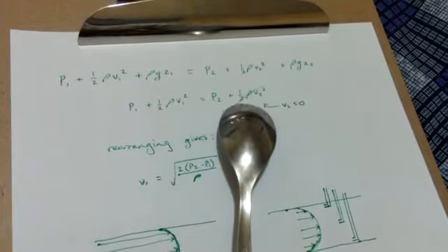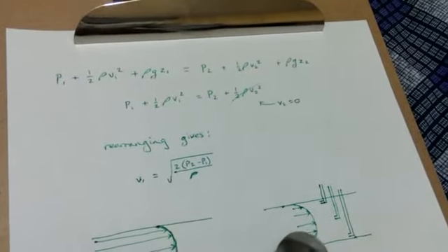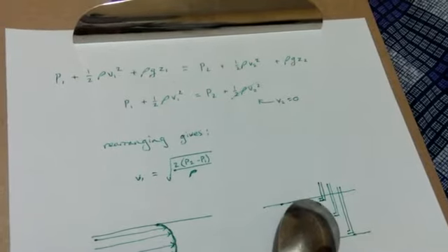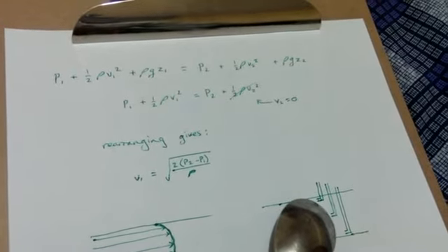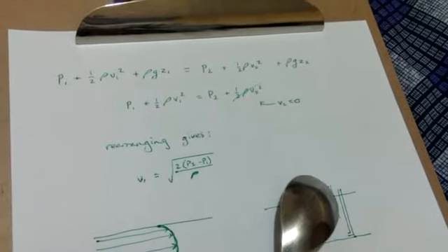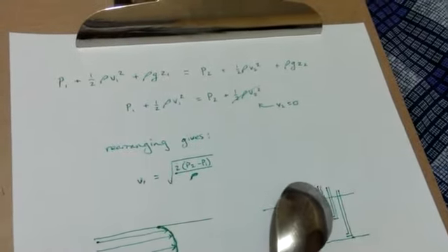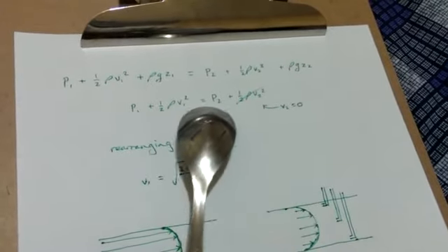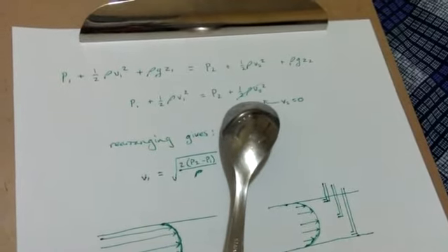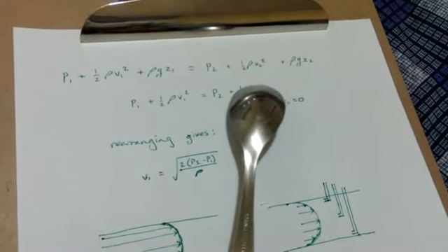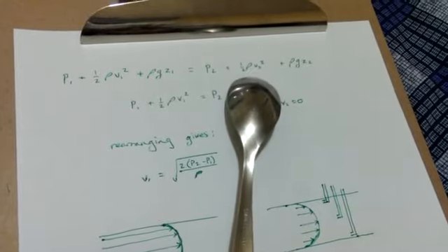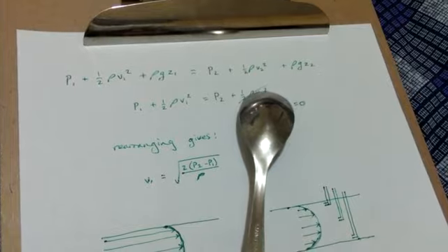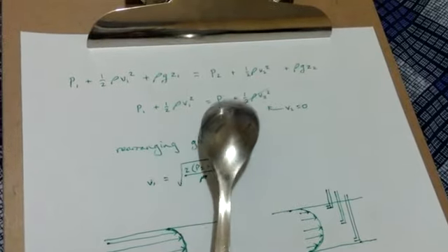Then, when you come down to here, you will know that a Pitot tube has a stagnation point right in front of the entrance, right in front of the orifice, where the velocity of the air is zero because of the build-up of the pressure inside the Pitot tube. Because of that, you can completely neglect this part, V2, of the Bernoulli equation as well, because V2 is zero, therefore all of that is zero. So you can just consider this part.